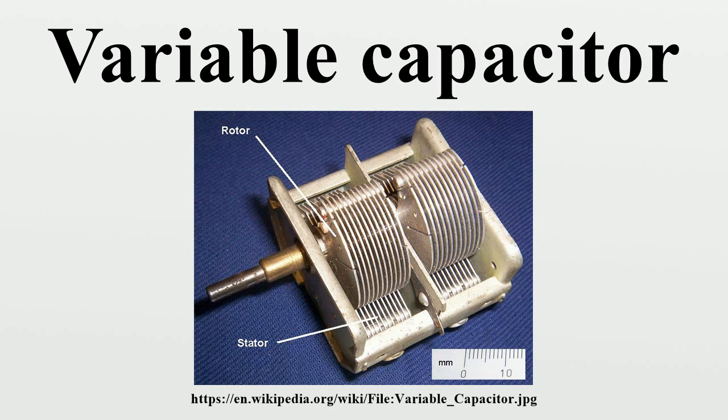MEMS is still a relatively new technology and has not yet been accepted broadly. BST devices are based on barium strontium titanate and vary the capacitance by applying high voltage to the device. The tuning accuracy is limited only by the accuracy of the DA converter circuitry that generates the high voltage. The limitations for BST are stability over temperature and linearity in demanding applications.